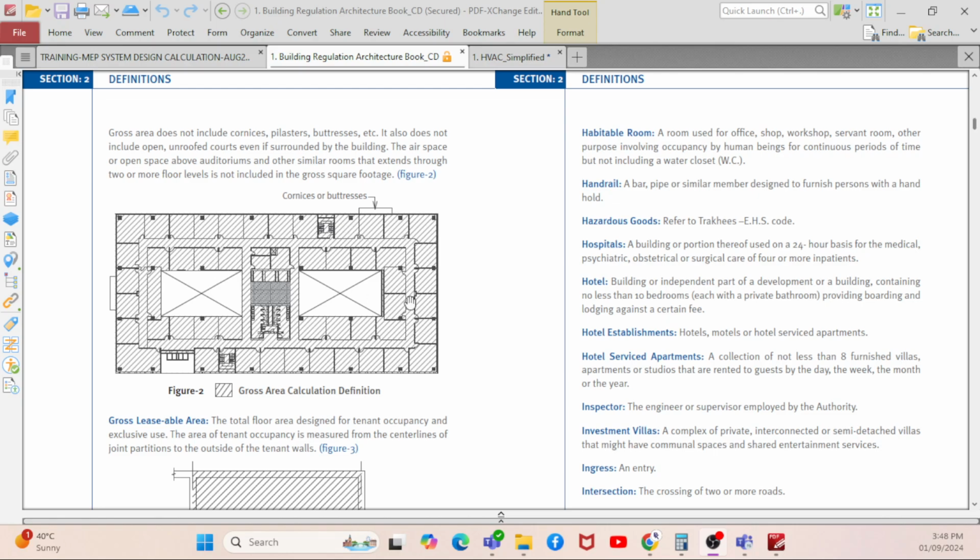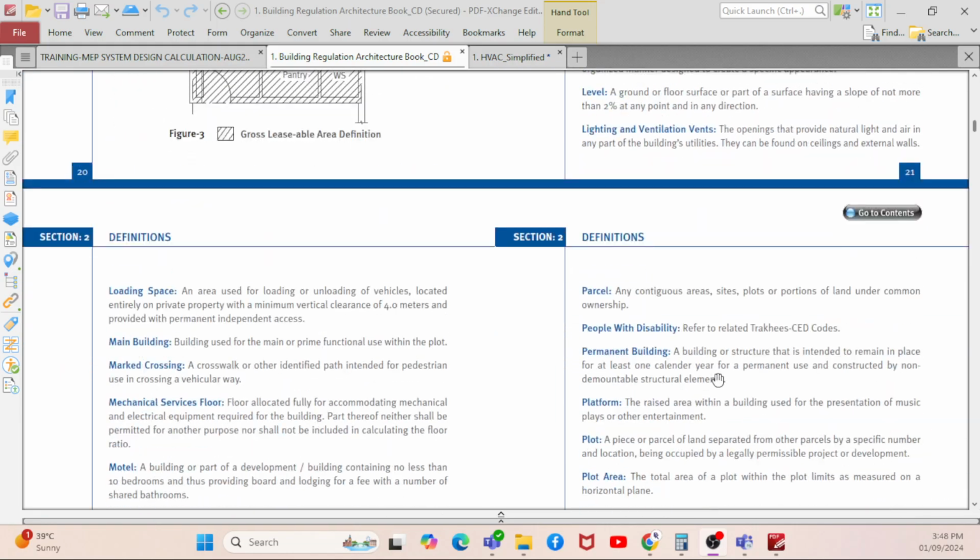Then there is a lift and toilet; I have to do the space planning for everything. When I do the space planning, I have to comply with the minimum requirement. Say, if I need 10 square meters based on the guideline, it is because 10 square meters is for human comfort. If I keep a very small room like 8 or 7 square meters, I may feel uncomfortable. So based on that standard, the architectural guideline has been developed. If you go further down,